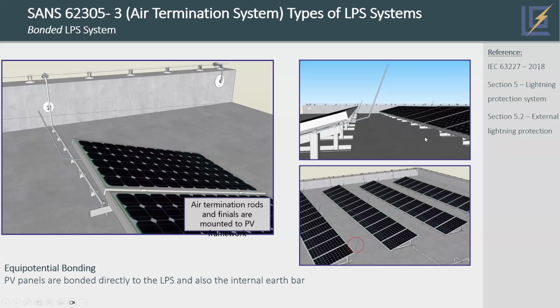I can test between, let's say, this solar panel frame and that structure, and there will be continuity, 100%, 0.2 ohms as per the standard. But if I take it from that Lumax clamp to the steel roof, 99% of the time there's no continuity because of that anodizing. So now the question is, the standard says your solar system must be electrically bonded.